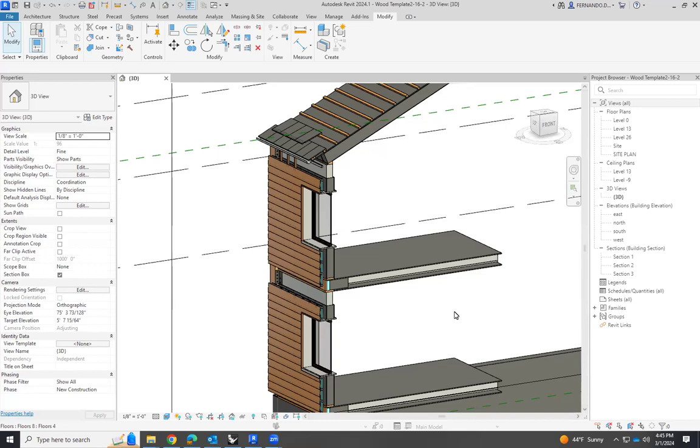Okay, so this is where we left off last time. Now we have to fix those small details, especially everything related to the thermal bridge here. Okay, so we have the roof, but where we have the structure, we have to interrupt the thermal insulation. And the same thing happens here on the first floor and here on the roof. Okay, and this is what happens in the real building.